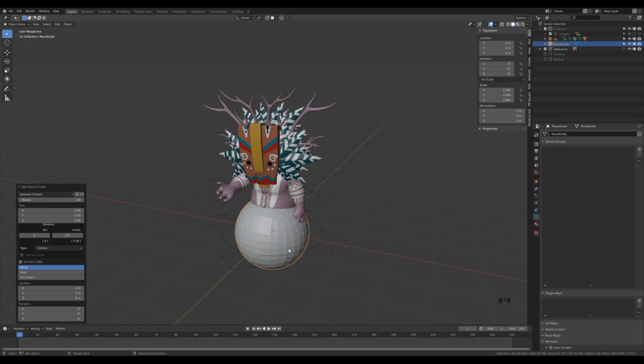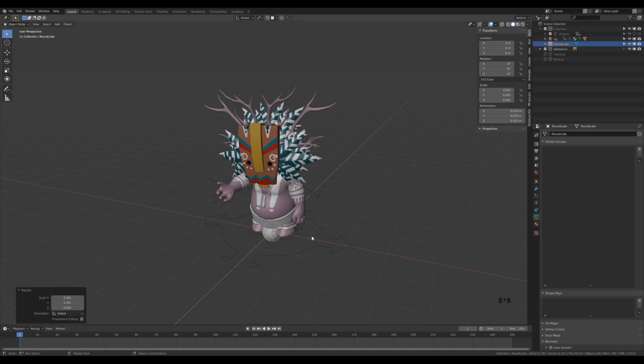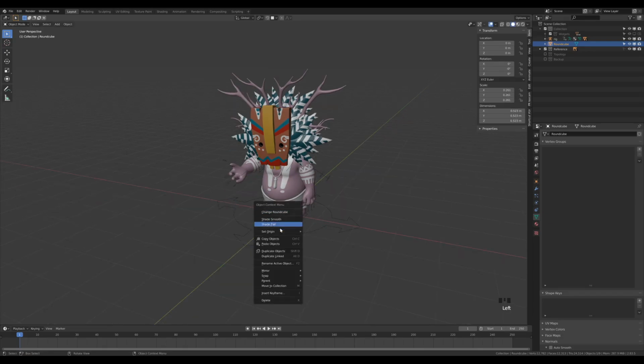And now I really want dense mesh for the sculpting, because the only thing that sculpting does is that it uses some kind of brushes that manipulate your mesh in a certain way. And to really be able to organically manipulate the mesh, you will need a much higher density of vertices and faces. So let's set this to 20. Let's confirm, and we'll make this a little bit smaller. So something like this, like you saw in the reference. And I will right click and choose smooth shading for this object here.